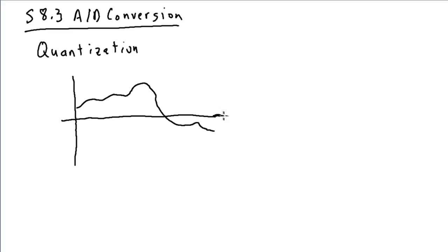So we've got something like this. Okay. And we're going to take samples of this waveform every capital T seconds. So these would be, for example, those particular sample values. At this point, we've just assumed that whatever these samples are, it might be 3.1567889, that we're able to represent these sample values exactly. But in practice, at least in the A to D conversion process, we have to convert these sample values into corresponding digital values.